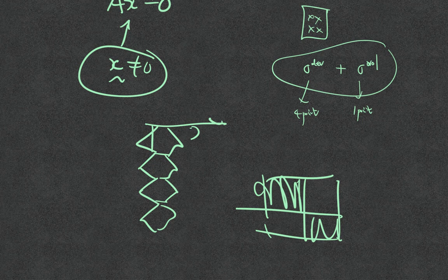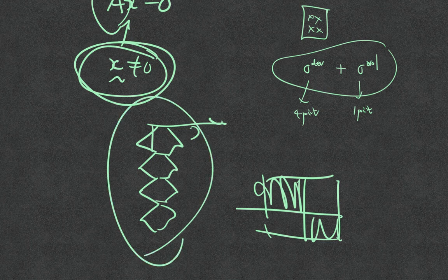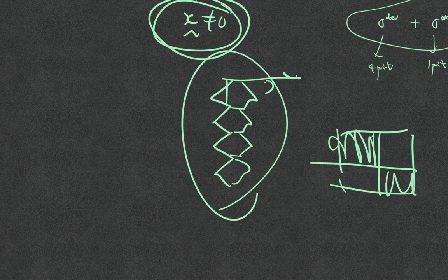People have to find that, and sometimes they use a trick: directly determine what the null space of that matrix is and then apply artificial stiffness to it so that you get rid of it. So even the basis for the null space will require some energy to trigger, and that can get rid of it. This is called hourglass control, because sometimes people think the mode looks like an hourglass. You know what an hourglass is? The thing where you put the sand and measure the time, it looks like this.